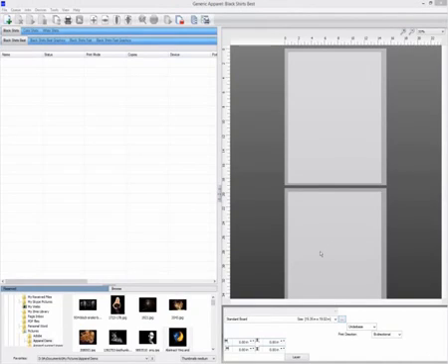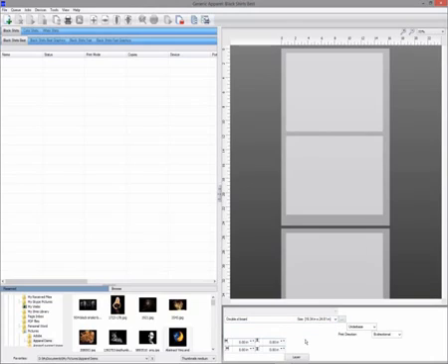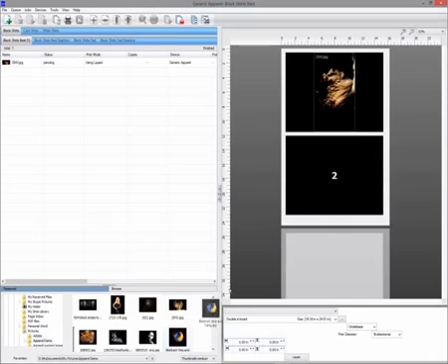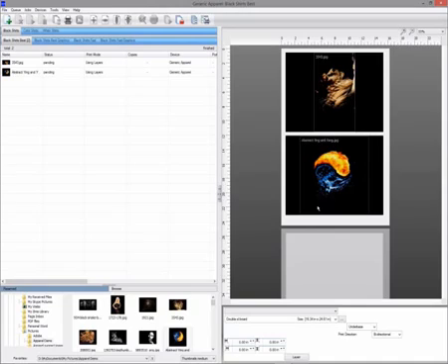You can use templates to lay out multiple images. For example, I have a template board that allows me to lay out and print 2 t-shirts at a time. By selecting my XXL board, I can see the board area and the 2 t-shirt print areas. This allows me to add 2 separate graphics, one for each t-shirt. As the neck of the t-shirt will be positioned on the left, this template rotates the graphics on import so that they are correctly positioned for printing.